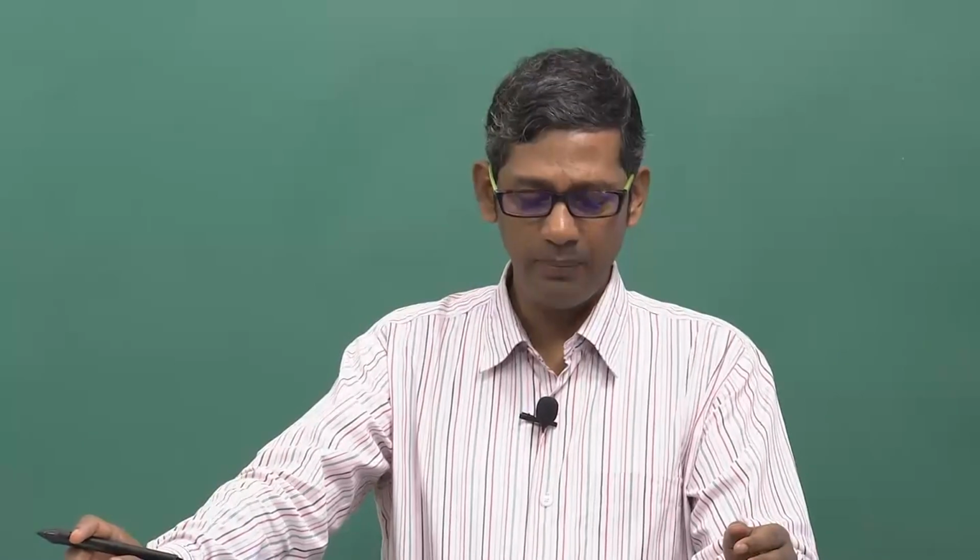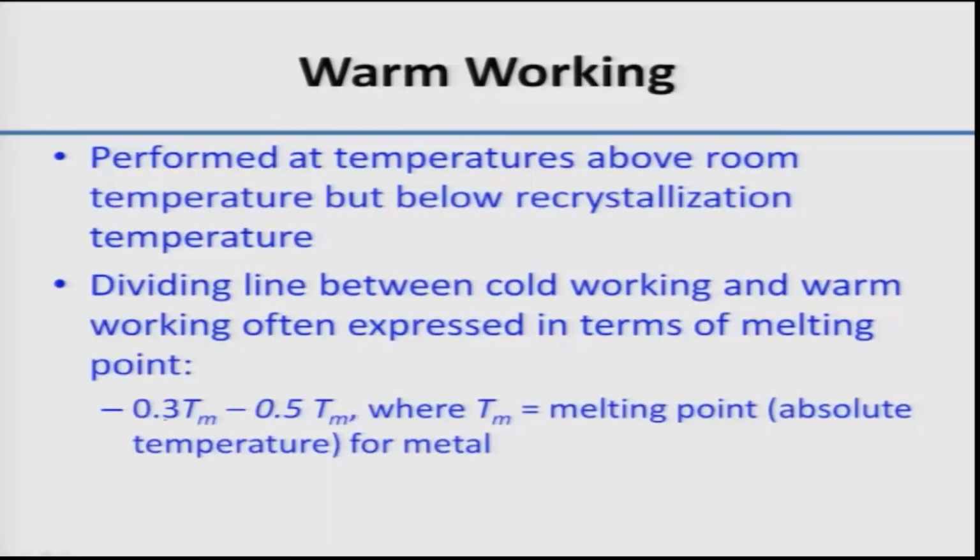For some metals it is better to use something known as warm working, not at such a low temperature, but in the temperature range between 0.3 Tm and 0.5 Tm. Materials are heated and deformed using these processing techniques like rolling, forging, extrusion or drawing operations.